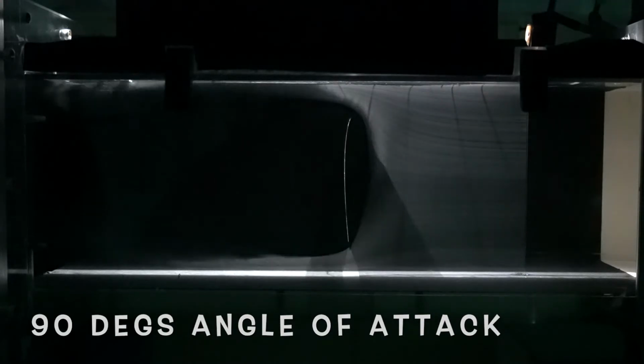And now we've bumped the angle of attack up close to 90 degrees. So this is our flat plate regime. You can see the shape of the airfoil no longer matters. What the flow sees is essentially just a flat plate. Doesn't matter that it's a NACA 0012 anymore. And so in this regime, we obviously have very extreme drags because of the conditions.